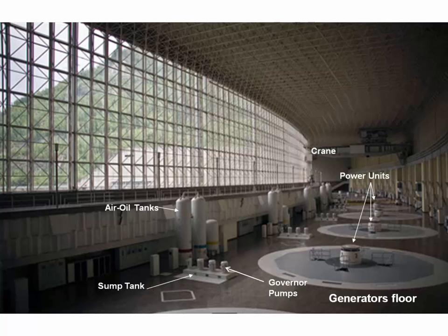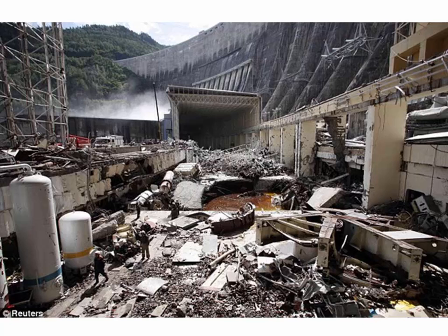They've got a very electricity-dominant industrial base that was in bad trouble for a few years as there was a series of explosions at the dam. Initially they wondered if it was terrorism or something, but upon further investigation they found out that the water was cavitating as it passed through the dam. What that means is the pressure was decreasing as water flowed through pipes inside of the dam to the point that the water was actually turning into water vapor because of a low pressure section inside of the pipes, and then the water bubbles, when they go back to a high pressure location, will collapse very quickly.